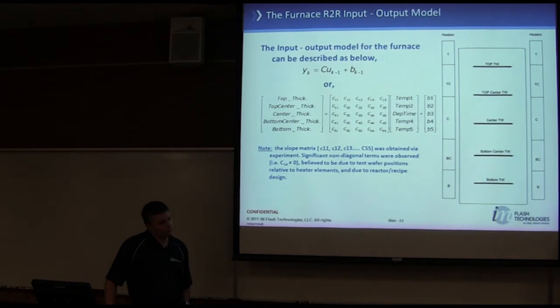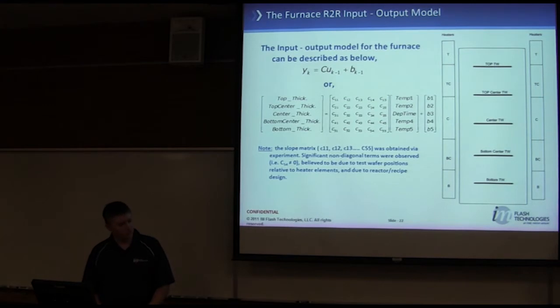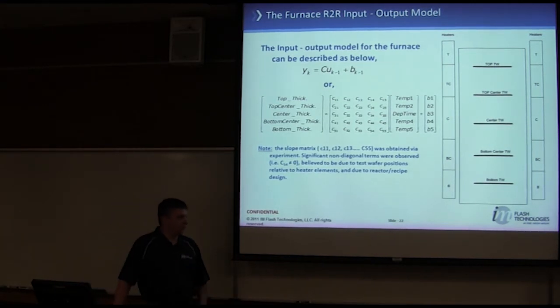So what we deem a critical step in our fab has to have a run-to-run control on it, because the process is capable of it. We just can't tune our chambers fast enough manually to make it manufacturable. And also you have process movement, so one tool might move whatever, 10 angstroms in a day or a week, and as that moves, we need to keep it on target.